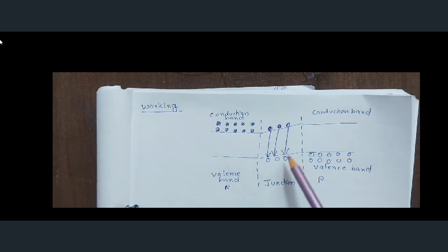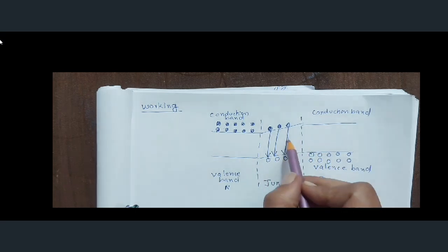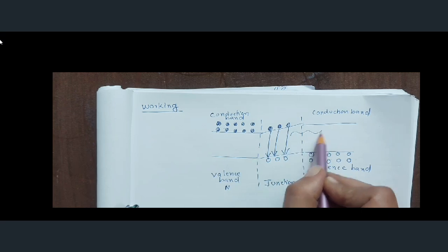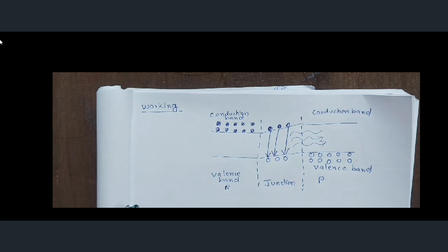When electrons and holes are there, what will happen next? They will recombine. So recombination will take place. For a small value of forward bias, the electrons and holes recombine. As they recombine, radiation will start coming out from here. The electron-hole recombination will bring about spontaneous non-coherent emission of photons in all directions. But for our laser to form, we need some important properties: one is coherence, second is monochromatic, and it should emerge in a particular direction only.